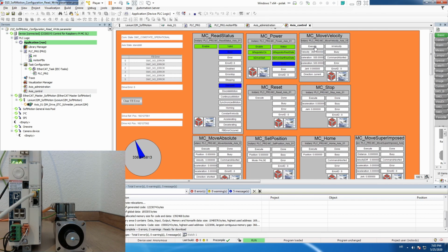That means that it's going to be 1 rotation per second or 60 rotations per minute. And RPMs is something that you feed your velocity loop inside the drive. And I will show you that SoftMotion already knows that and it does it correctly.